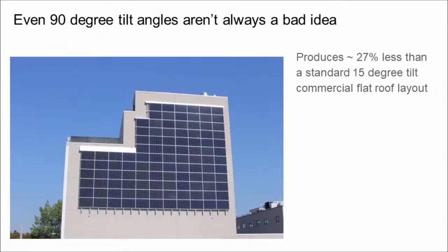You can find solar arrays bolted 90 degrees down the sides of buildings, such as in New York City, where electricity is expensive and rooftops are cramped, or for off-grid power in Canada to avoid snowfall. Similarly, at a shallow tilt angle, the north side of the roof isn't off limits. So while east and west facing solar arrays are perfectly fine site selection spots, and even north-facing solar arrays in some circumstances are acceptable, most solar in the northern hemisphere faces south.